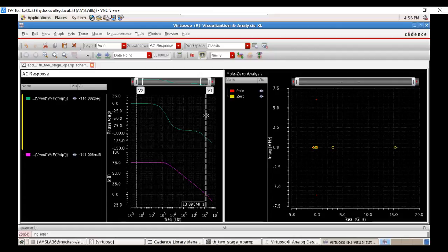So essentially the unity gain bandwidth will decrease, definitely. You know why it will decrease, right? Because we are shifting towards lower frequency. This will become sharper here at this point itself. So this crossing frequency will decrease. Okay. Thank you. No worries.